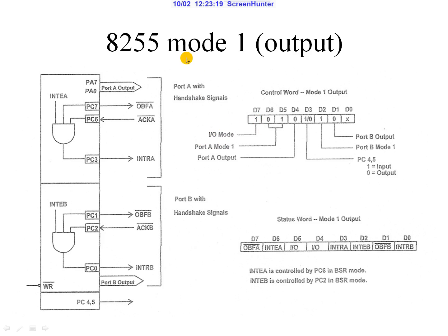And the input output mode is going to be given as 1, because we are going to use this for Mode 1, so we will be selecting 1. Port A is going to be Mode 1, and port A is going to be output mode, so that is being selected here. For port B we can choose others also, that is, these particular pin bits are going to be set for port B. It is an output and it is going to be operated in Mode 1.